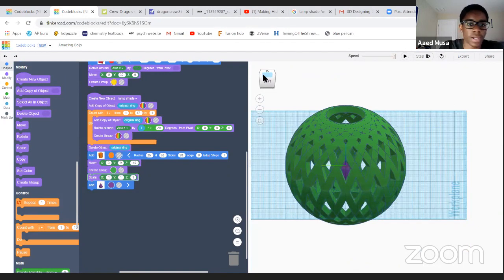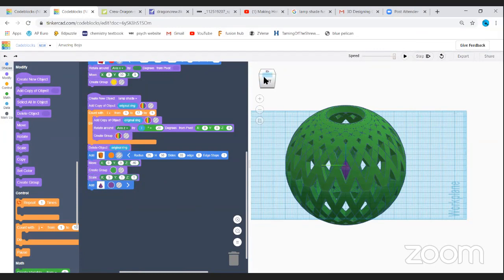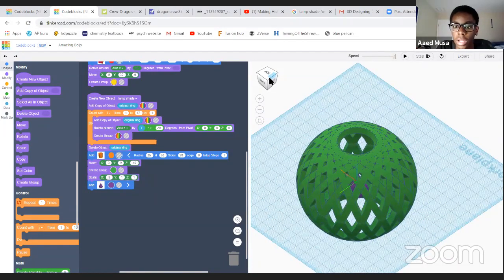So any object that you make, its scale is just automatically 1, 1, and 1 for X, Y, and Z. And 1 is just the default. So think of 1, 1 is kind of the 0 in this situation, and that's just with scale. So if we were to decrease our number, let's say I wanted to make X 0.5, which is half, what do you think would happen? It would get squished halfway. Yes. So a number less than 1 would make the object smaller on that axis. And a number greater than 1, what would a number greater than 1 do?